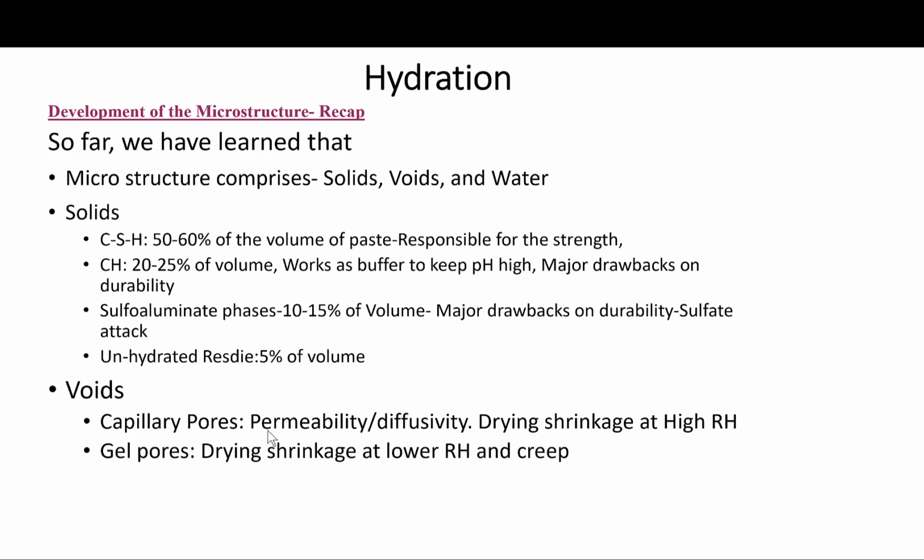The voids: we have the capillary pores, which impact permeability and diffusivity, and drying shrinkage at high relative humidity. We have the gel pores, which impact drying shrinkage at lower humidity and creep.